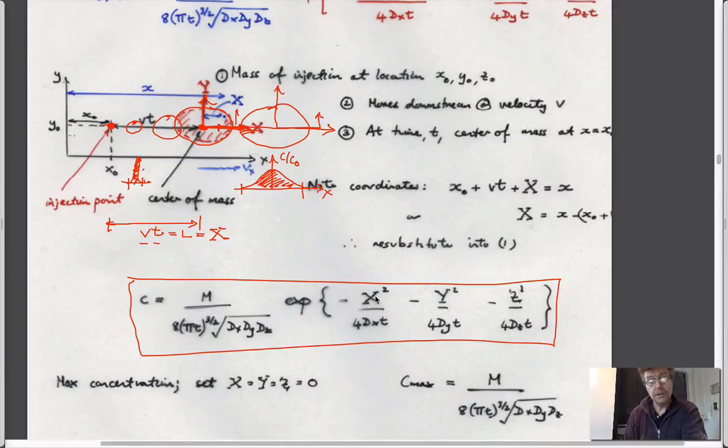And so you see these terms, a length squared, a dispersion magnitude, and a time. It's an exponential of that, and so these terms should be non-dimensional. So this is length squared, this is length squared over time, times time. So these indeed have no dimensions. And instead of working in concentration, this is the amount of mass that's put into the system. If you like, the mass of solute. So in other words, milligrams or kilograms, it doesn't really matter. And again, that should be equivalent to some magnitude. This is non-dimensional. This is a concentration, so I guess this should be a mass per unit volume.